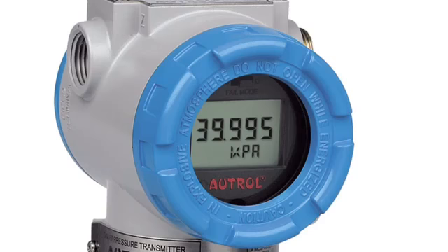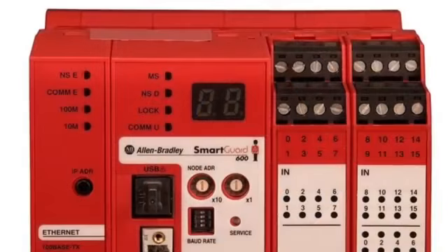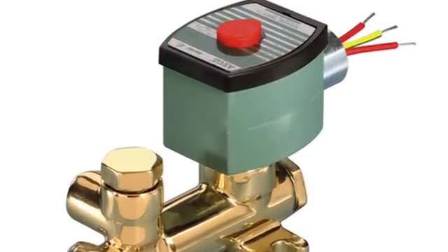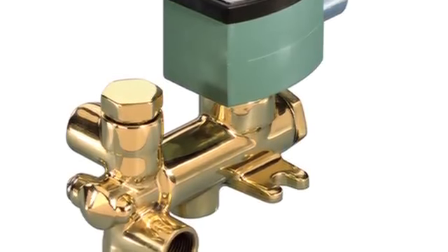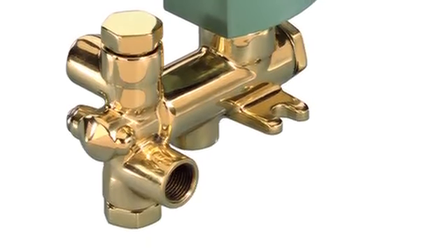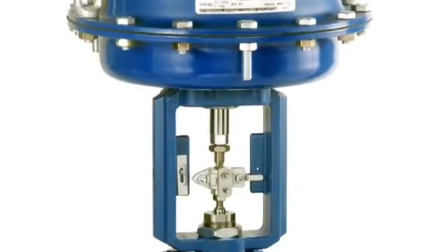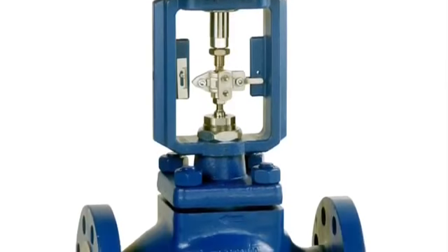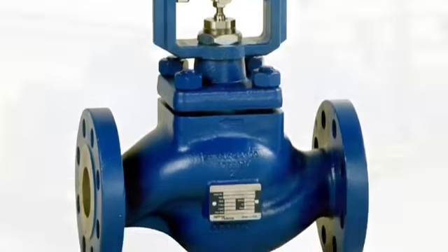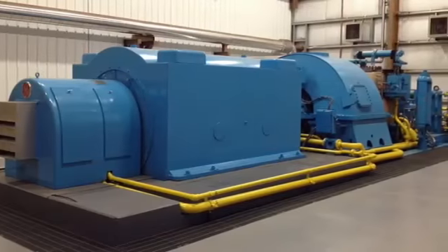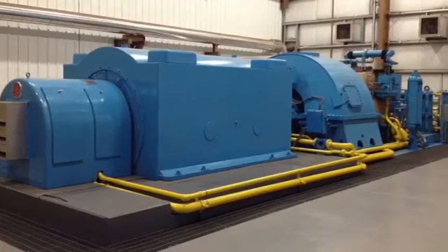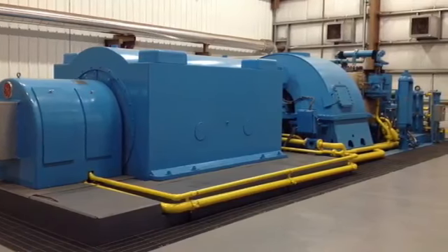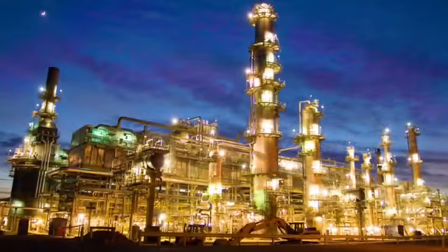As you can see, there are a lot of components that must operate as designed to shut down the turbine generator in the event that an abnormal condition exists. Examples of abnormal conditions may include low lubrication oil pressure, high lubrication oil temperature, steam pressure that's too high, inadequate plant air pressure, etc. In order to decrease the safety instrumented function's probability to fail on demand, all of the functions described here must work flawlessly. What could go wrong?